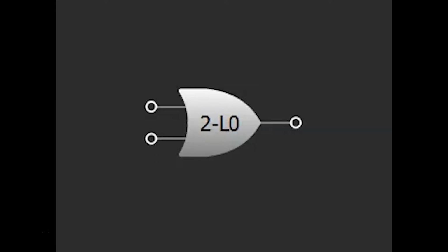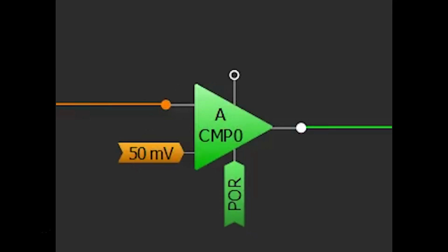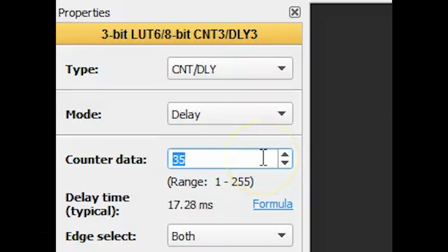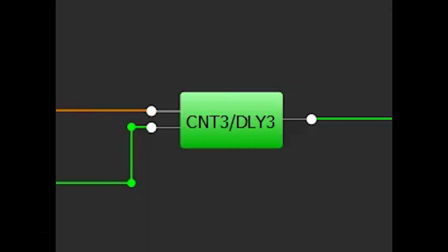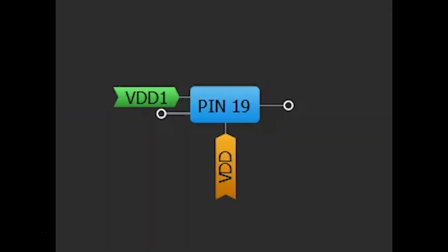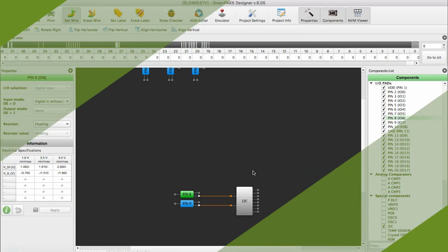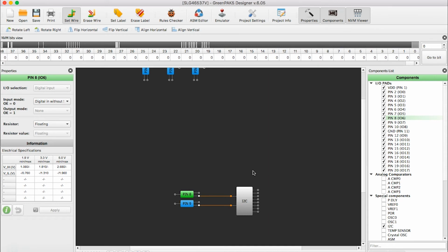With this functionality, you could change the logic of lookup tables, adjust analog comparator thresholds, tweak timings or change clock sources, and even make a GPIO expander by tying the outputs either high or low. Let's look at some special additions to the I2C functionality.